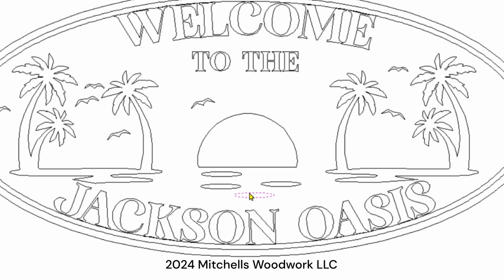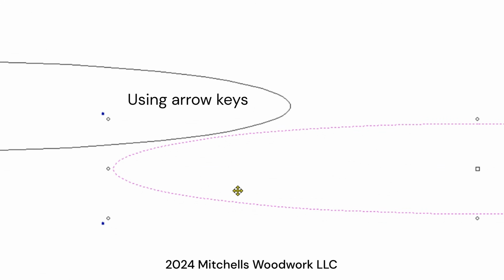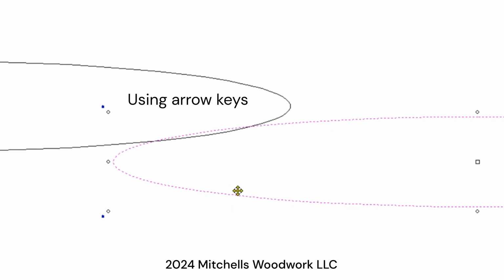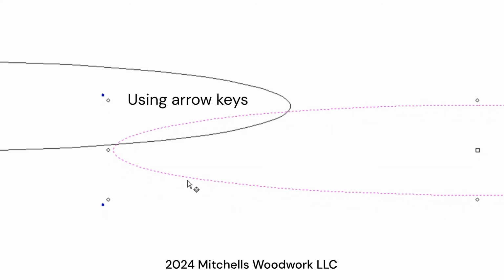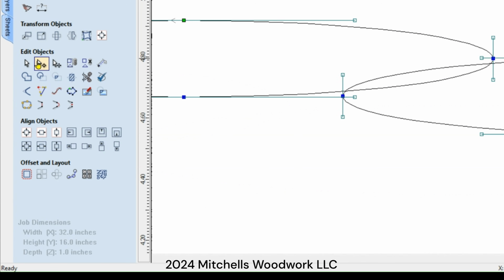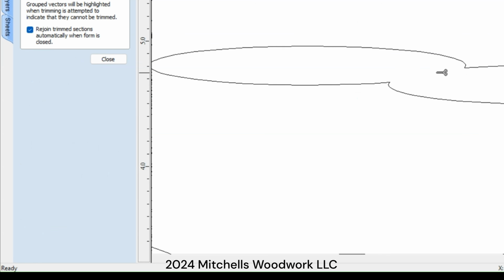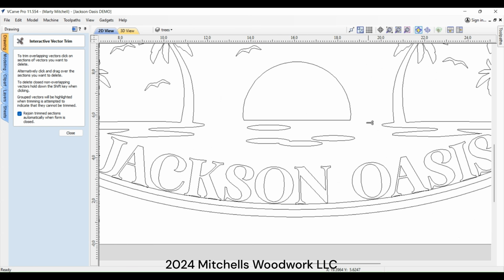Well, let's say we wanted to join a couple of these. So let's join these two here. So we'll move it over up till it makes contact. Let me zoom in there. Okay, go a little bit more right there. All right, and then highlight both of those. Click on Node Edit. Go to your scissors and just snip away what's in the middle there, and then back out, and then you've got 2 of them. A longer one, 2 of them there, and that's a simple way to do that.